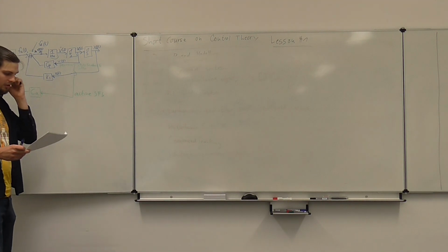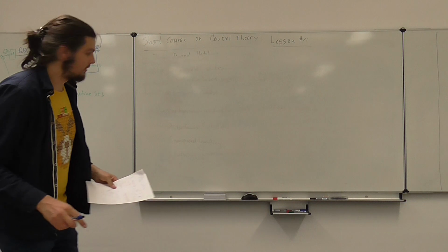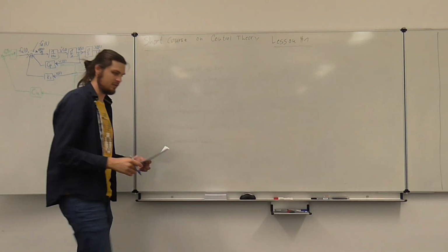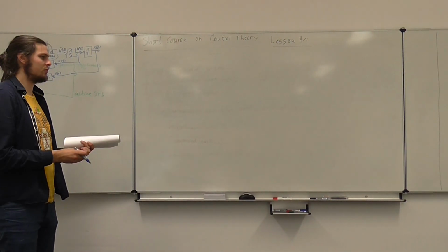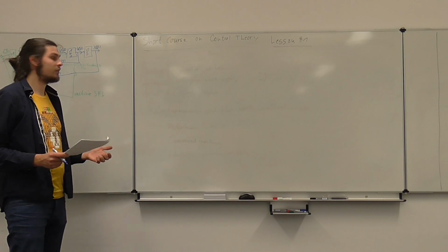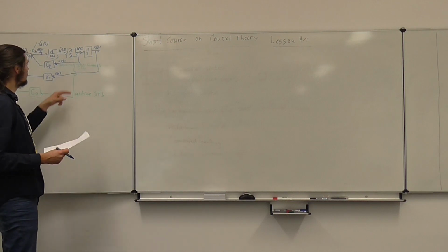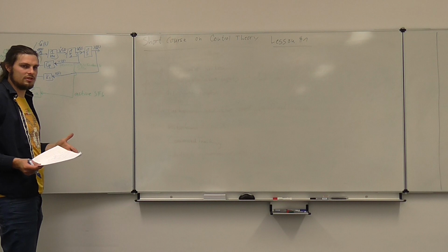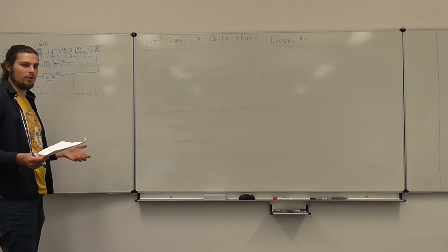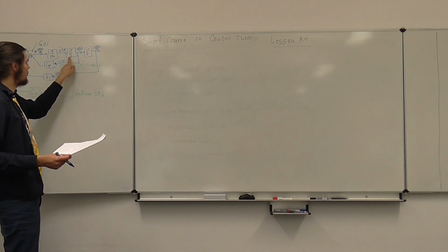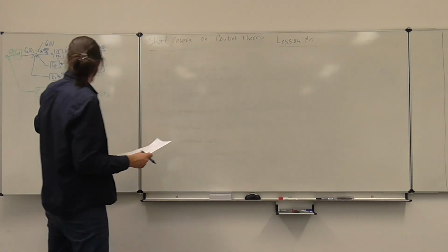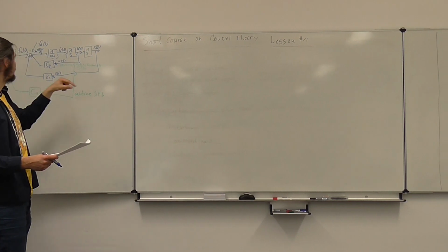So now we want to talk about transfer functions and attributes of this that we can use to dynamically tell what our system is doing. To know the dynamic performance, we usually go into the Laplacian domain. It really helps us, right? These are integrators, and we can use just these integrators if our system is linear. If it's non-linear, Fourier transformation or Laplace transformation doesn't work, right? In this case, it's a linear system, so we could replace just the integrator with 1 over s. And that's very nice because now it's very easy to get a transfer function.